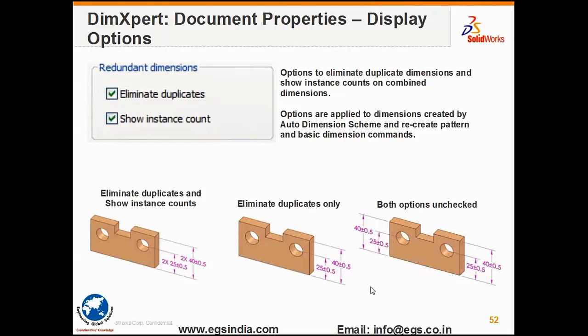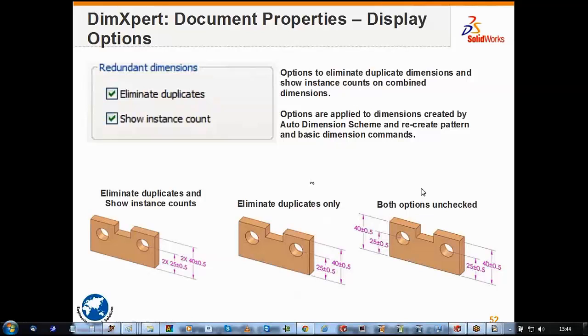Now, one of the advantages is you can eliminate the redundant dimensions as shown on the left pane over there, which helps you to avoid confusion downstream in manufacturing. This is a very important thing that is required in all aspects of manufacturing to prevent that ambiguity. So elimination of duplications is avoided with this approach, and it's a check in place.